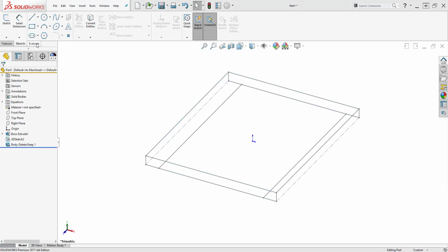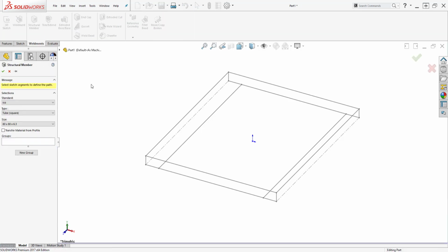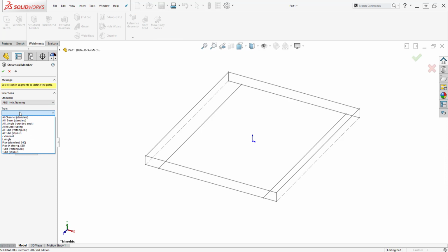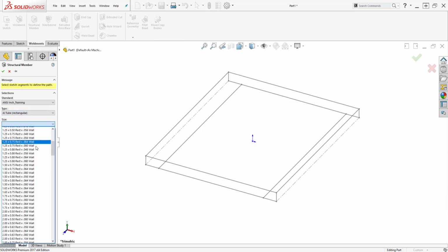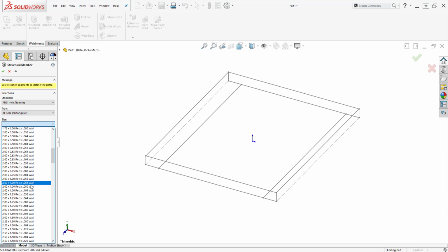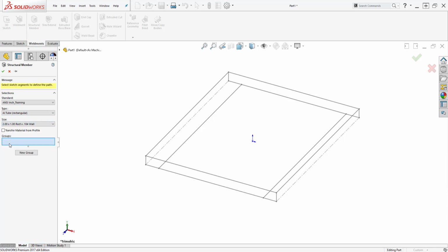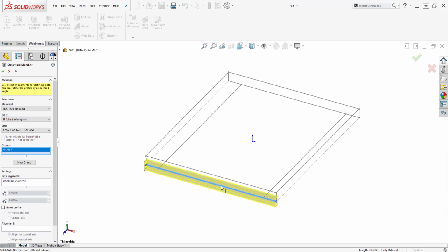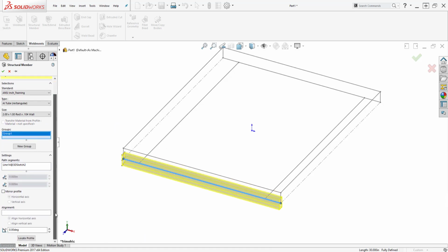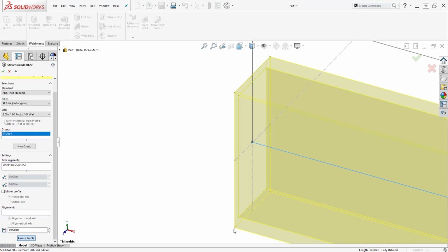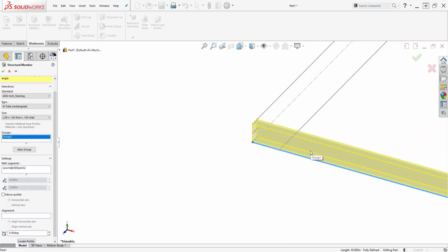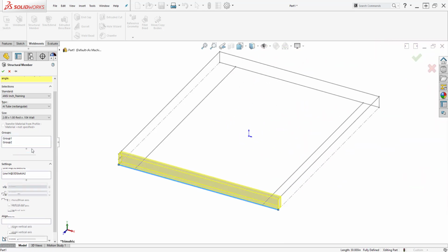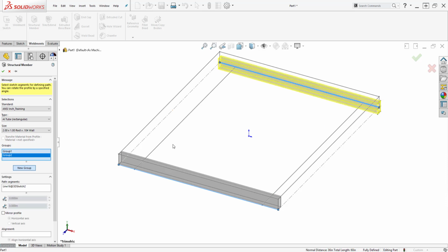At this point, we're going to add the aluminum drive rails and supportive framing for the robot. Setting up weldment libraries is something you will need to do no matter what CAD system you use, but I will put a link in the description for how to do that in SolidWorks if you've not been trained on this. I picked the same aluminum wall thickness for my 2x1 that VexPro sells because the VexPro aluminum is pre-drilled and makes placing the frame square during the construction a breeze. Since the extrusion has a hole every 1 inch, we will use this number later to square everything up.